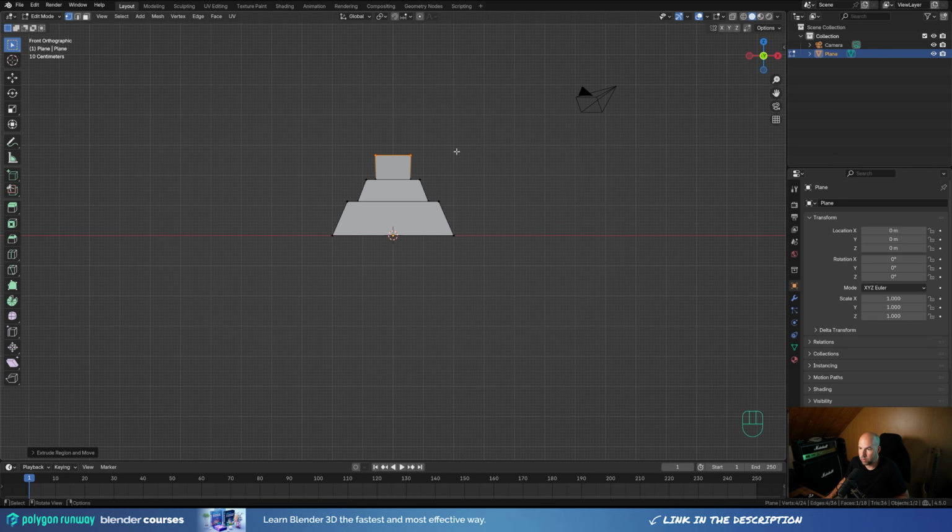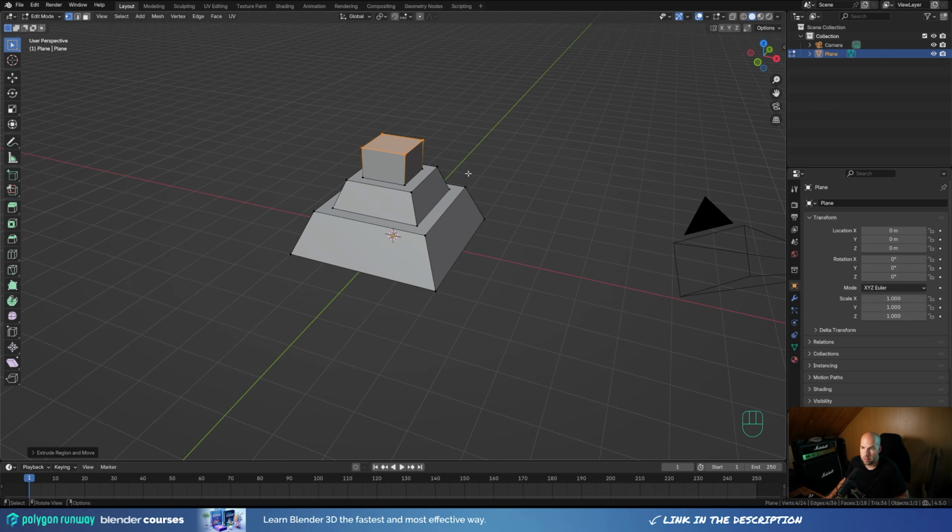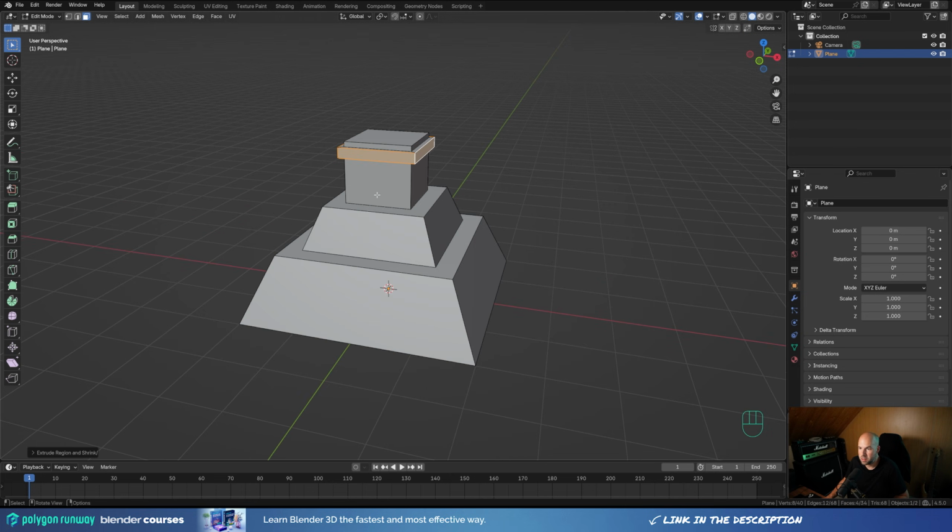And now finally we'll do some decorations there, so let's press E to extrude, and one more time, then press 3 for face select, or click right here. Alt click this loop and press Alt E and extrude faces along normals, just like this. And we can press S to maintain even scaling and continue and confirm with left click. And now we'll extrude some openings in there, so let's press Ctrl R and create the cut right here.